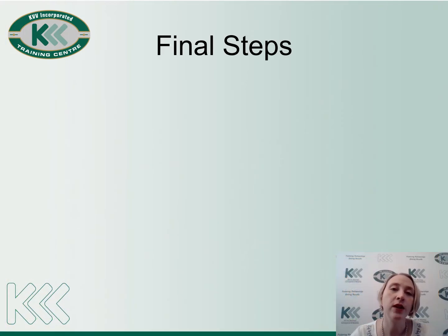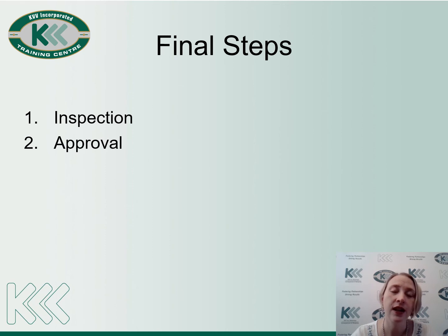Once your property has been completed, the municipality will send out an inspector to confirm that the property was actually built in terms of the approved building plans. If you are lodging as-built plans, in other words, your property has already been completed without plans and now you are lodging plans after the fact, the municipality will also send out an inspector at this point to confirm that the property is built in accordance with the building plans presented to the municipality and will then approve the building plans after the sign-off of the inspection.